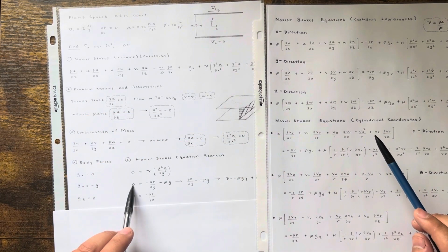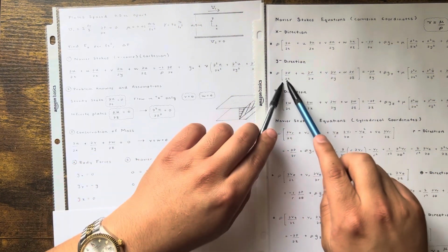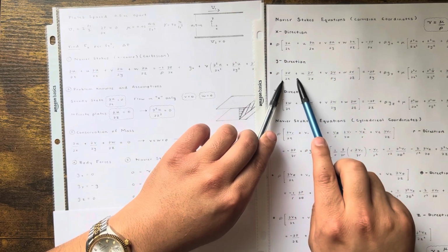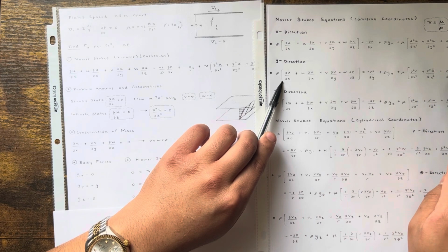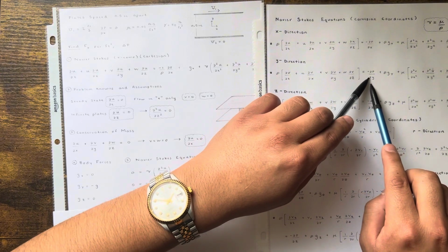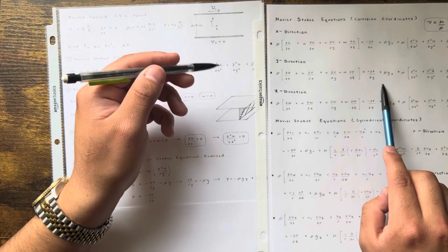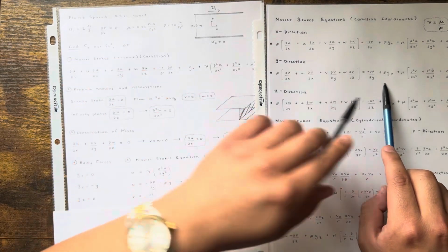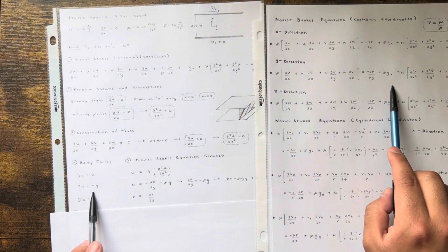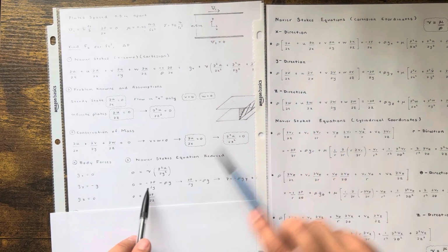And then in the y direction, let's go ahead and do it. Well, we know v is 0, right? So look at the y direction. v is 0, so all these terms go away. Now you're left with these two. There's a pressure gradient in the y direction. That's what the problem is asking you: how does pressure vary from top to bottom? And then we know gy is active, because gy is a negative g. And that's what I got here. My Navier-Stokes equation for the y component reduced to this right here.